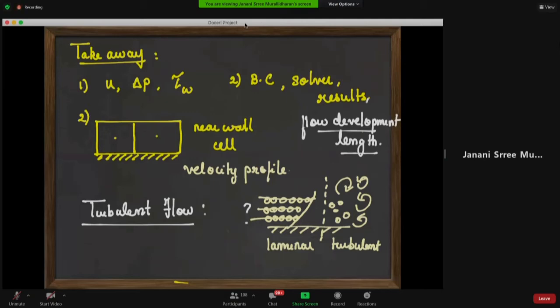But as a CFD professional, now the question lies as to how am I going to capture this variation in velocity? This variation in velocity for such a complex eddy-like circulating structure, right? What is my velocity, say, at this location, right? What is my velocity at this location from the wall? How do I track what the velocity will be for a turbulent flow?